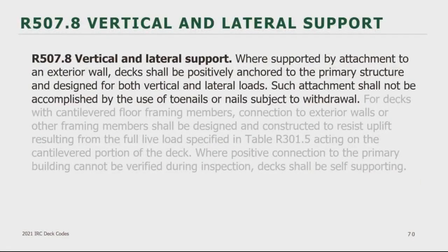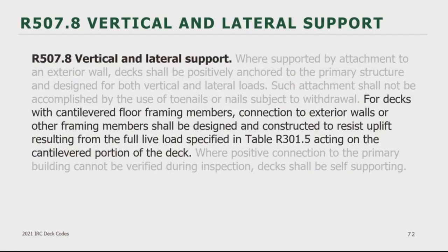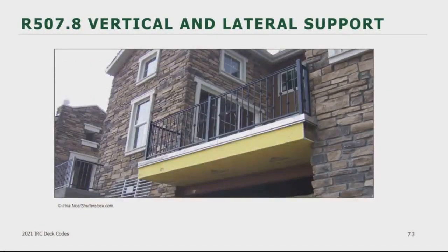If you have a deck that utilizes floor framing members from inside the house that cantilever out, you will have to check that for uplift forces on the underside of the deck. A high uplift load from wind on the outside could cause the floor joist to fail inside the house depending on loading factors. A structural analysis is needed for any deck constructed like that. Here's an example of what I'm talking about here. The floor joists from the deck are actually cantilevered floor joists from inside the house. So this will need structural analysis on that uplift.